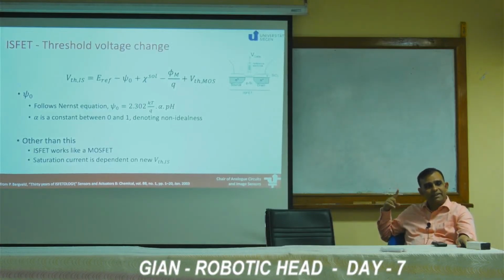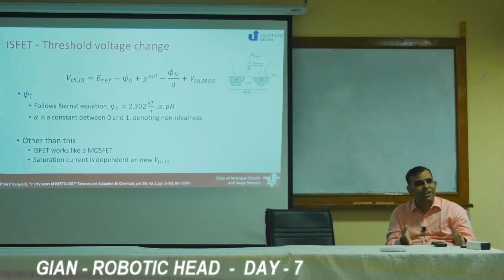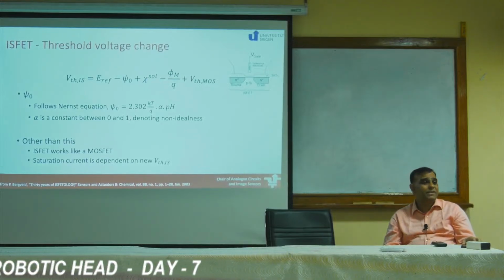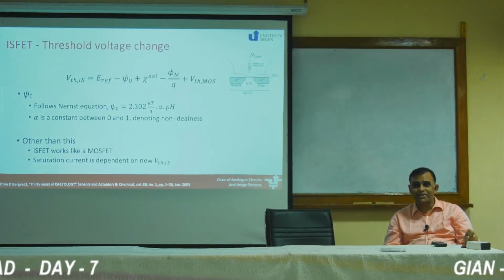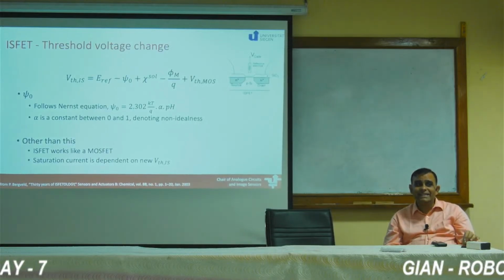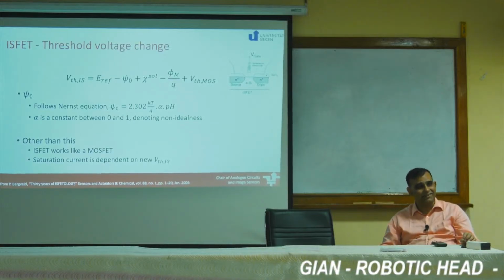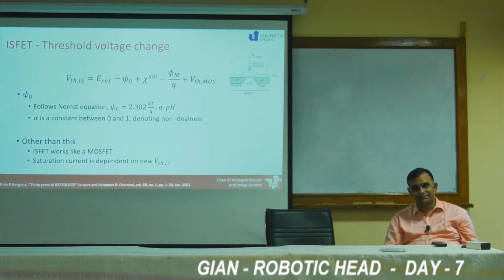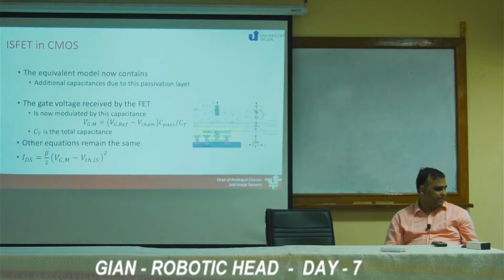Right? Yesterday when we were looking at sensor properties, we said a sensor should just measure what I'm trying to sense, not everything else. But because it's a function of temperature, it's going to be temperature dependent, including my pH measurement. So, if I am making an ISFET as a pH sensor, I also need in parallel a temperature sensor to measure the absolute temperature to compensate for these effects. Okay? If I may move forward.